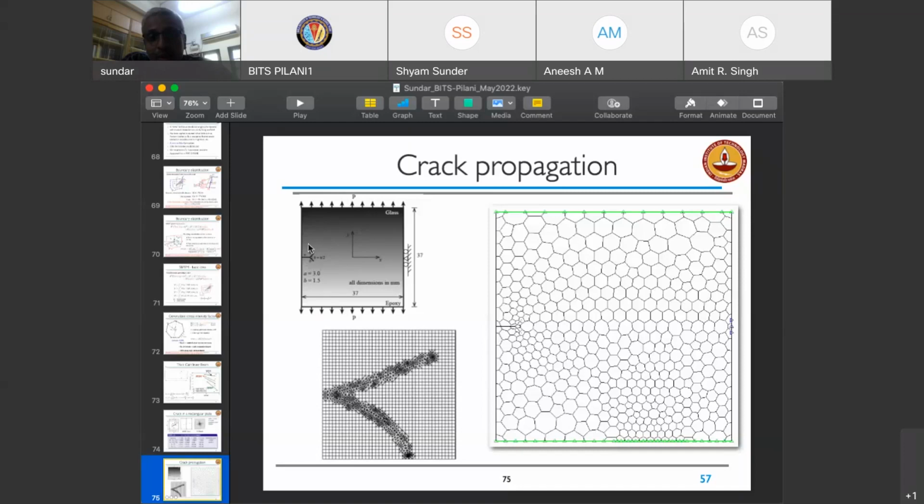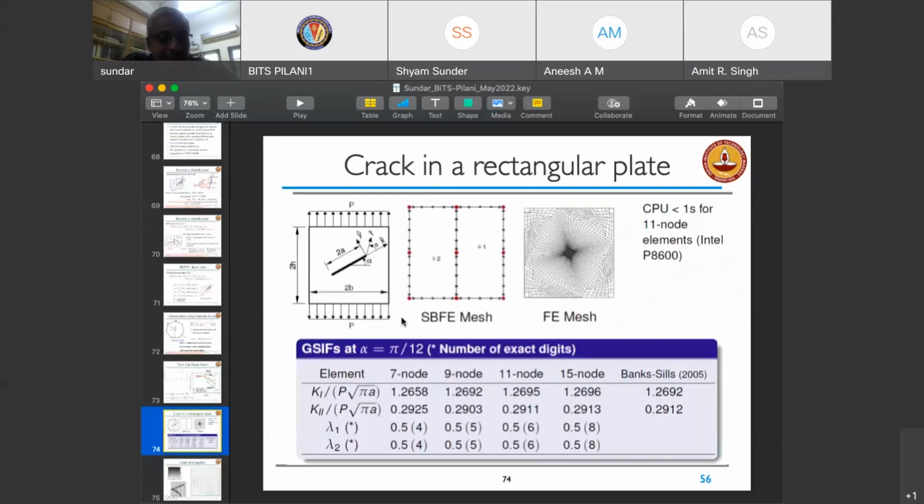So one way to do it would be to divide it into smaller regions. So in this example, if I create the scaling center here, this becomes a concave region, so I will not be able to see this part of the domain. That's the reason why I have divided it into two regions, where from each scaling center I will be able to see the entire domain, which will then allow me to solve the problem.